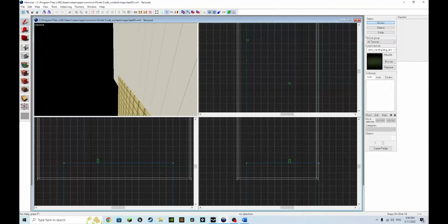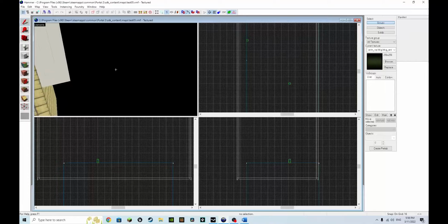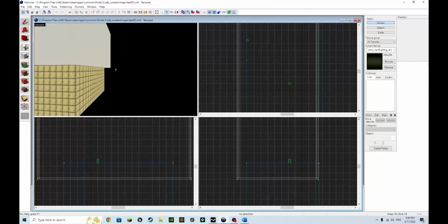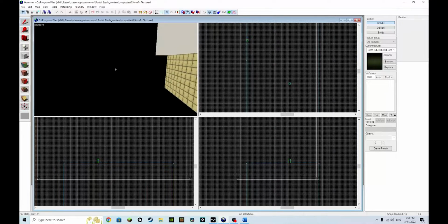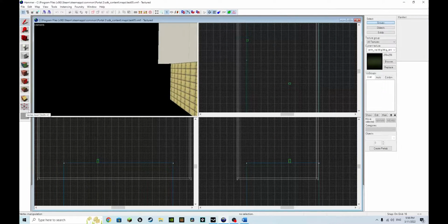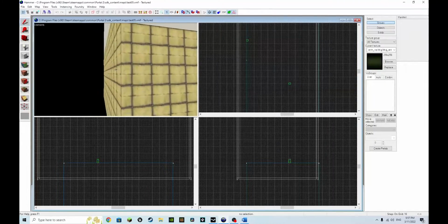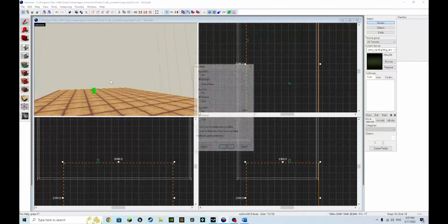Okay, so I found out what was the issue, and when I started it up, it asked me if I'd like to remove an invalid solid. So if you remember my first object that I placed, it was actually invalid because I think I used a few vertex manipulation. How do you pronounce that tool? The vertex tool. So I think that might have been why it didn't compile properly, but now it should.